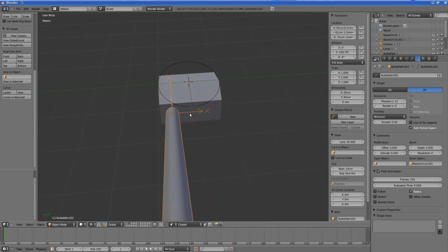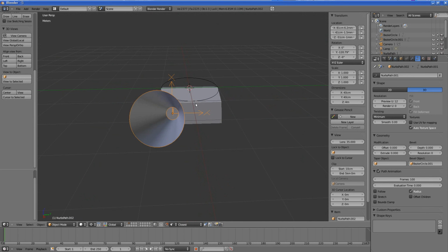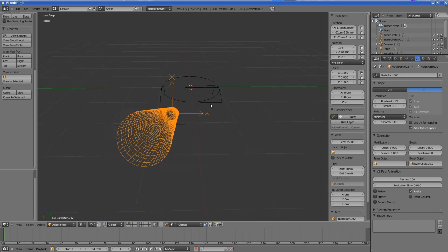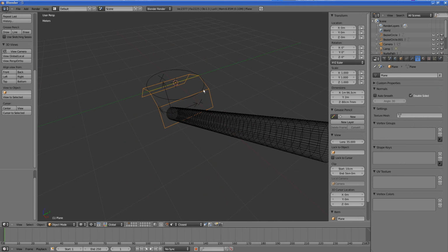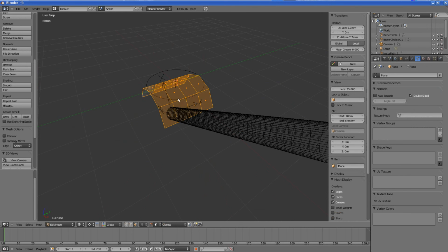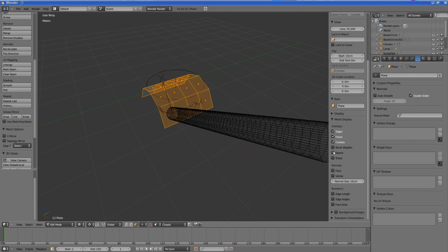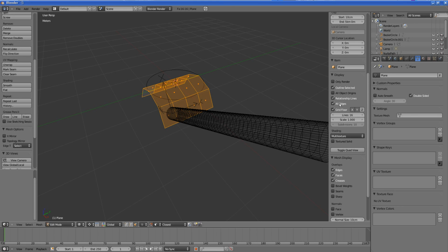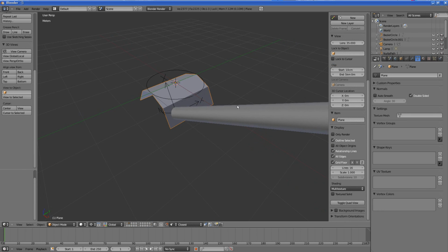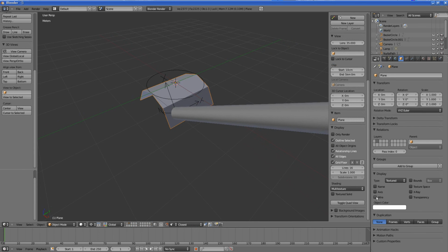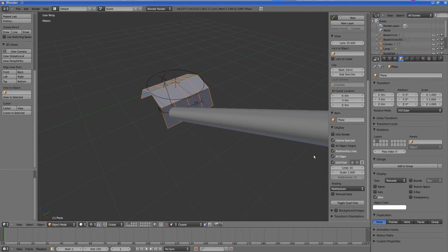And now let's duplicate, let's go to the wireframe mode. You'll notice that on this mesh you don't see all the faces. Okay, it has 16 faces. That's because we need to turn on display all edges. Okay, and then in the object mode, turn on the wireframe. Again, if you remove this, sometimes it won't show all the edges.